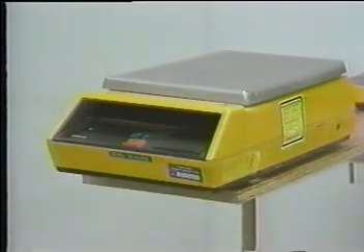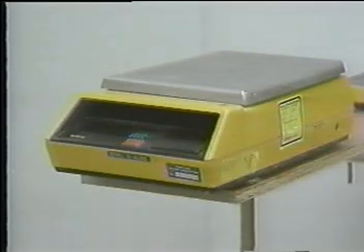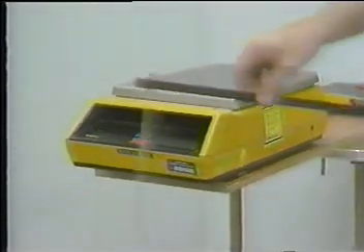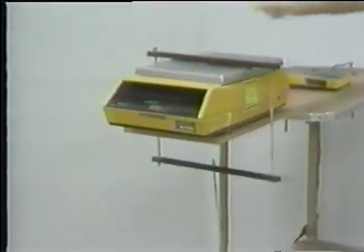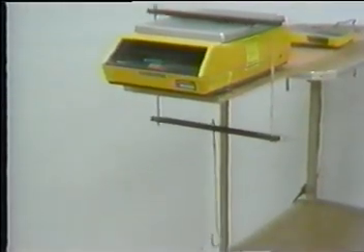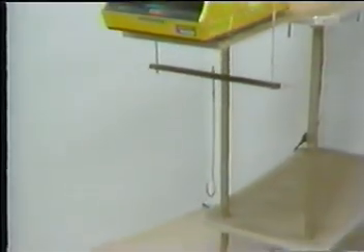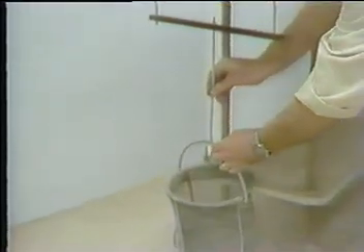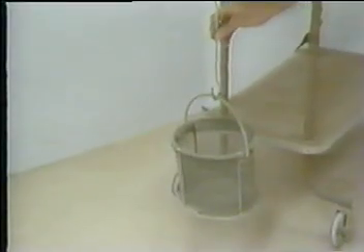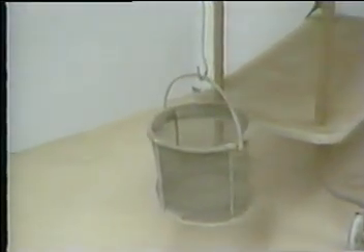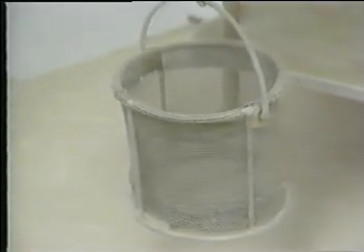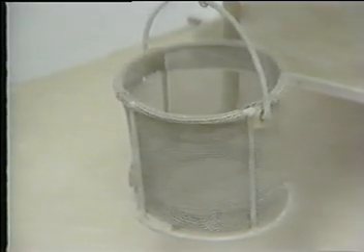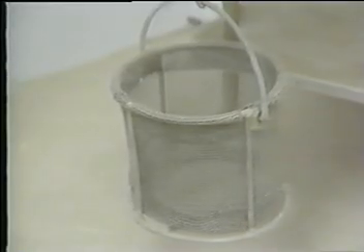sample weight within the range of this test, or 0.5 grams, whichever is greater. The scale or balance should have a suitable apparatus for suspending a sample container in water from the center of the weighing platform or pan. A sample container, a basket of 3.35 millimeters or finer wire mesh, or a bucket of approximately equal breadth and height with a capacity of from 4 to 7 liters for aggregate samples up to 1.5 inches nominal maximum size.